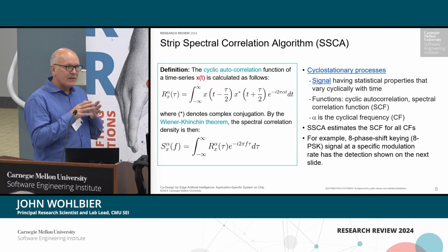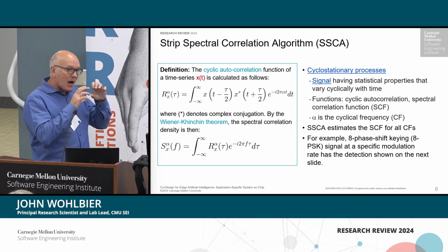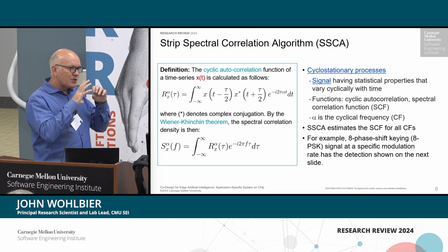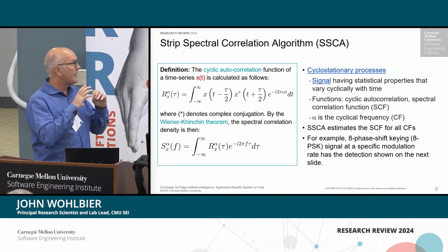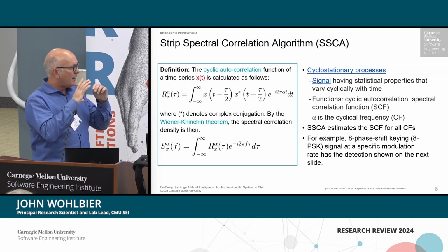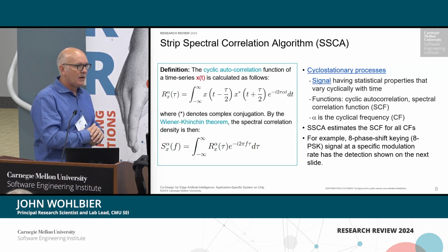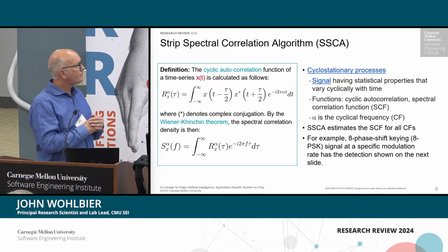What does all that mean? Well, you have these high frequency carriers that are being modulated, and the modulation rate is much slower than the carrier frequency rate. If that modulation rate has this periodic behavior at a slow pace on the high frequency carrier, that's going to tell you something about how the information has been encoded onto the waveform.